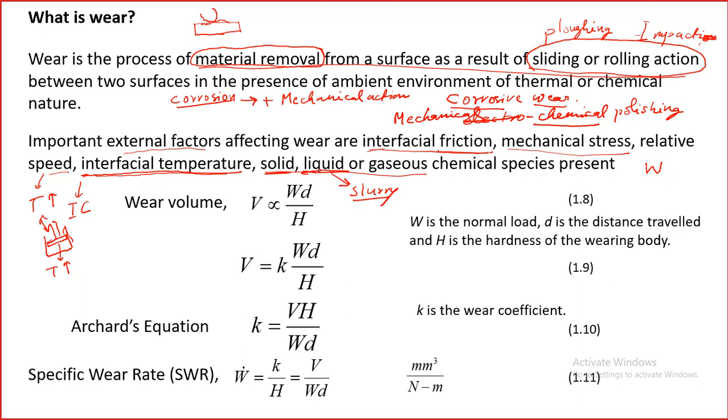In that case, these liquid particles or liquid droplets will actually attack the surface, so there is a lot of impact also happening. Not just liquid, there will be solid particles as well. It can also be only liquid. Because of liquid flow as well, there can be some wear process, especially in pipe bends.